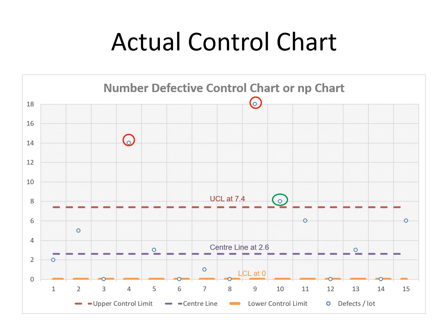After that, we'll discuss the third chart. Finally, we come to the third kind of quality control charts for attributes, which we call the C bar chart or the defectives per unit chart. This kind of chart is used where the concept of lot is not there. That is, whatever is being manufactured is not getting manufactured in lots of equal sizes.